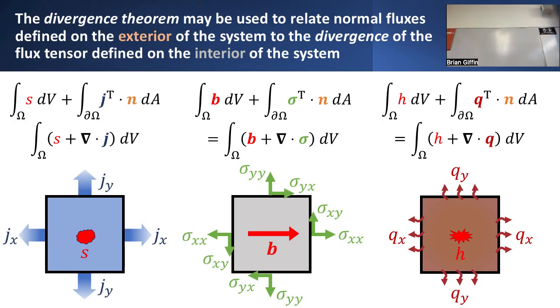In the case of this summation of forces acting on this cube of interest, we can do a similar thing, applying the divergence theorem to this exterior boundary integral that's integrating the exterior traction that acts over the whole boundary of this cube. And it turns out it looks kind of similar. In this case, what we get is what's sometimes called the stress divergence. So rather than taking sigma, the stress tensor, dot product with n integrated over the boundary, now it becomes the divergence of the stress tensor integrated over the volume.